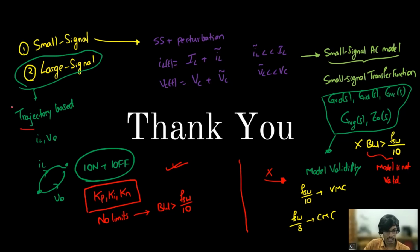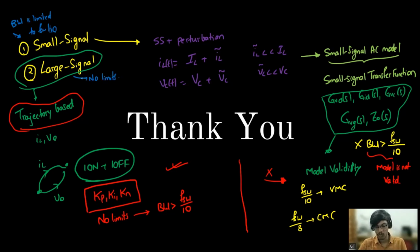So sir has considered the trajectory based, and there are no limitations. We can design a controller using both the methods, but here the bandwidth is limited to 1/10 of the switching frequency. But with the large signal method there are no limitations, and we can design the controller beyond a bandwidth of 1/10 of the switching frequency, which sir has shown, and I think he has also shown the hardware simulation results. Yeah, that is all about small signal, large signal. So in order to achieve higher bandwidth, which is not possible in small signal because of the model validity, we are going for the large signal tuning.